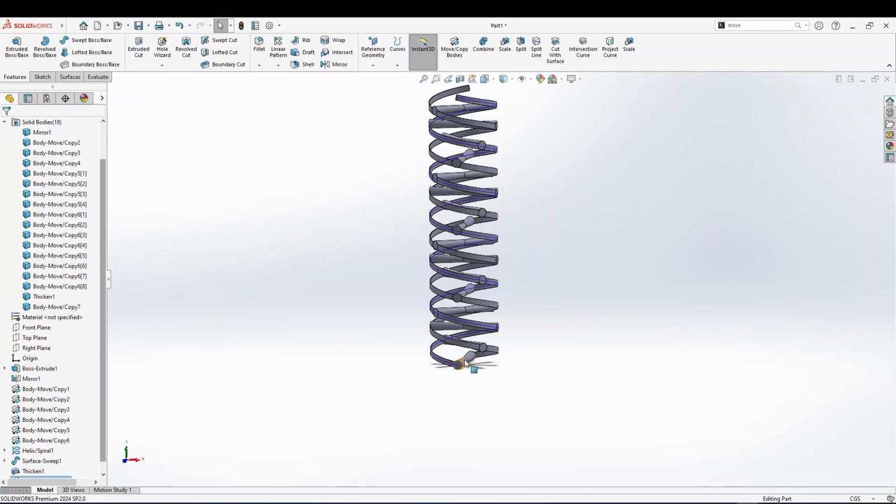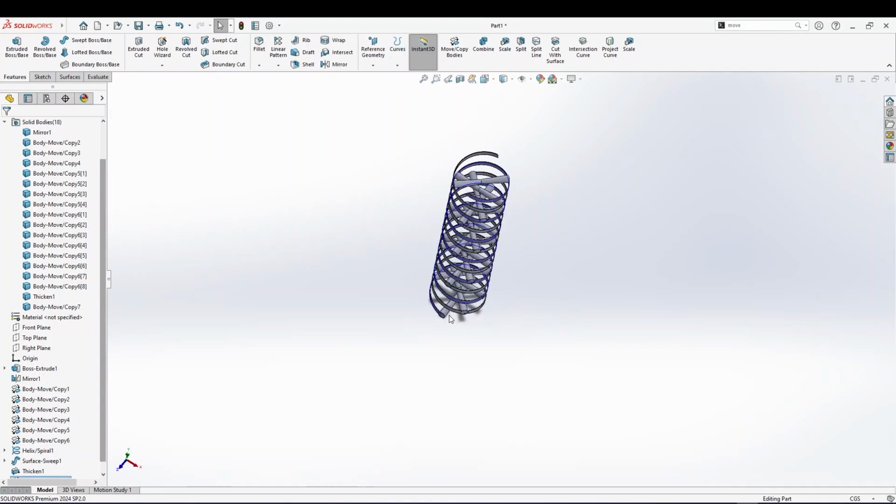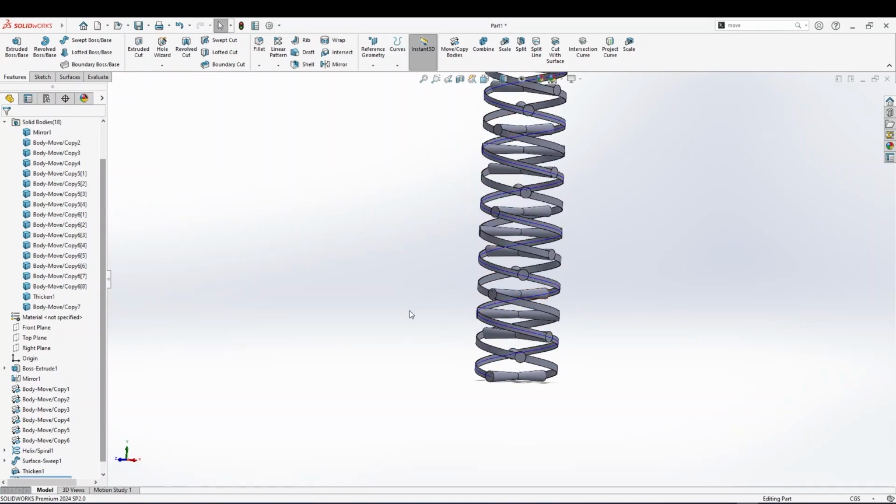Once again, when I want to understand where to move anything or where to stretch or scale, I should look right here on the left corner of my screen, because it shows me the position of the x-axis, y-axis, and z-axis with respect to my model. When you press the middle mouse button and rotate your model, this one rotates together with you, and at any instance you can see the standard axes with respect to your model, and it allows you to quickly understand what rotation parameters you need here.